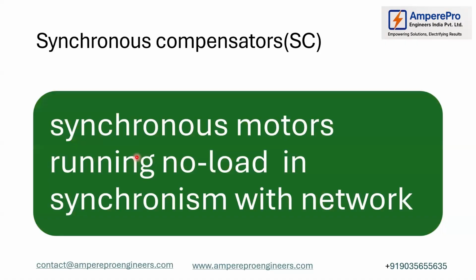The synchronous motor running at no load is used in big networks, where you feel the reactive power support is not sufficient at a certain voltage. At that time they will connect it. This motor is like a generator again, so it occupies quite a lot of space, and you need to give separate excitation.